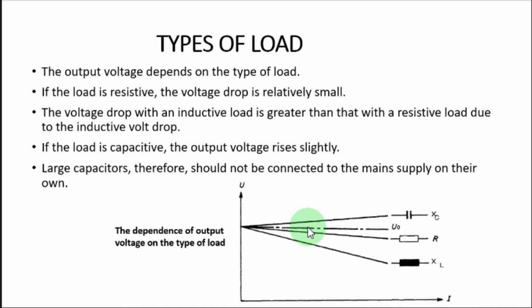And using the short circuit test, you short circuit the secondary and set the primary voltage to a value which will let the rated current flow on the primary side and the secondary side. And then you measure the input power. So this input power basically represents the copper losses on the transformer.